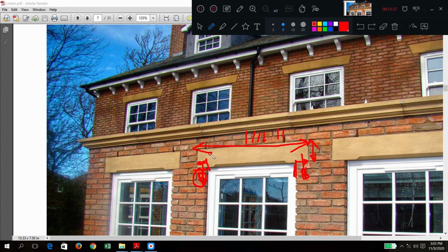Again I repeat, a lintel is a horizontal member situated above an opening. The opening may be a passage, corridor, door, window, etc. The lintel supports the wall or masonry on top, because there is an opening or gap acting as a passage, so it transfers the load to the sides using bearings. I hope it is now clear.